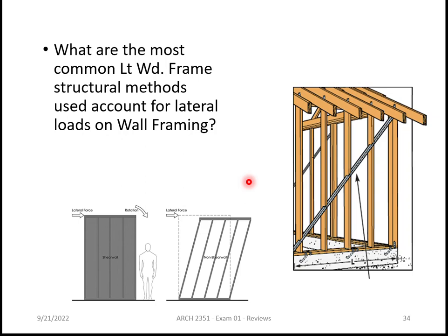But a common thing to do used to be to use diagonal bracing. It's an L-shaped piece of metal. They put a slight cut into the studs, and then they nail it across. Once again, they're triangulating. They're creating a triangle of structure, because a triangle can't deform unless you change the angle or the length of the legs.